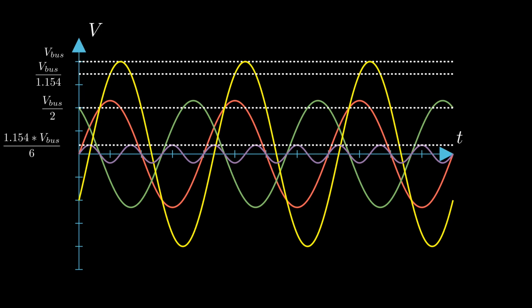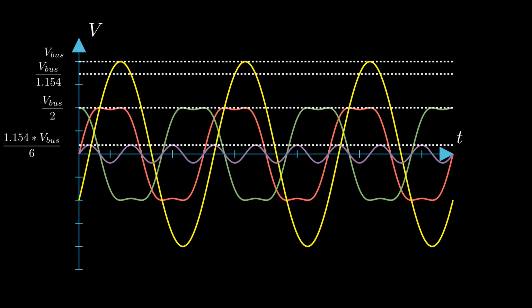This makes sure that the sine waves with the increased amplitude don't exceed their absolute limit, since the third harmonic subtracts from the peaks of the main sine waves. However, since there is only one harmonic, meaning it isn't phase shifted by 120 degrees between the phases or anything, the difference between the phase voltages cancels out the third harmonic, and only the main sine wave with the increased amplitude is taken into account. So this third harmonic allows us to increase our phase voltage amplitude by around 15%, and thus reach the voltage limit for the sinusoidal voltage differentials.